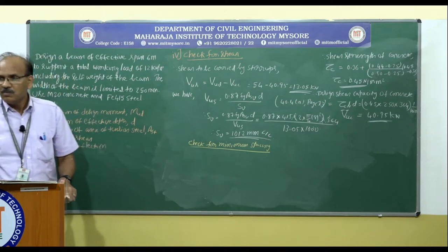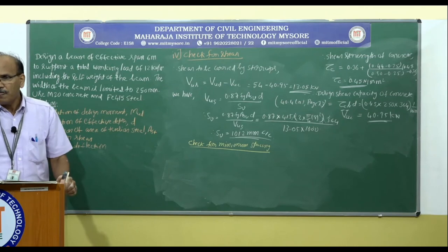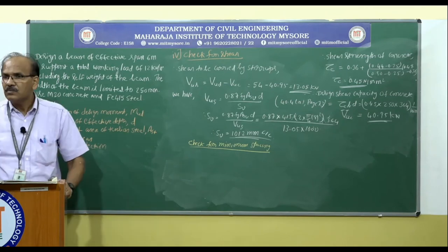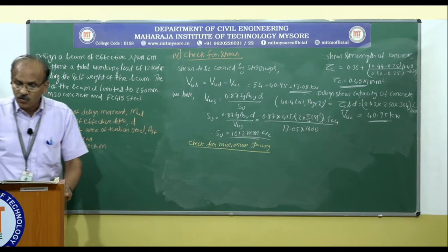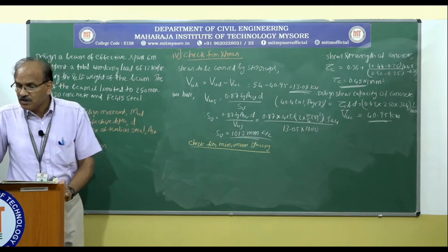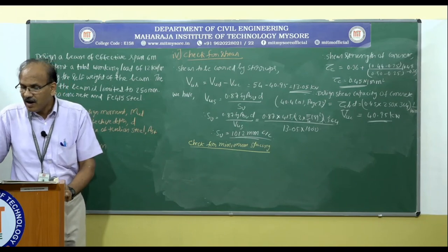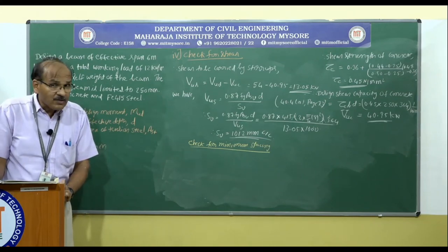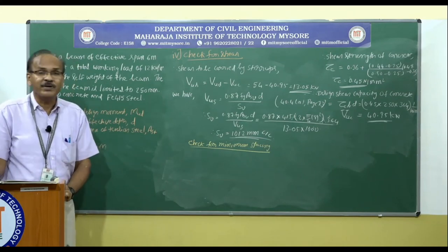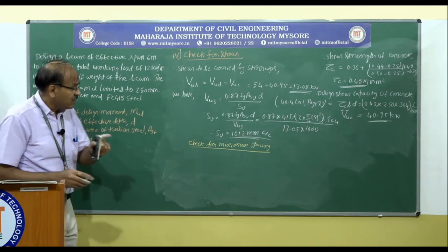And also the code says the spacing should not exceed 0.75D and in no case it should exceed 300 millimeter. Those are the two conditions, that is